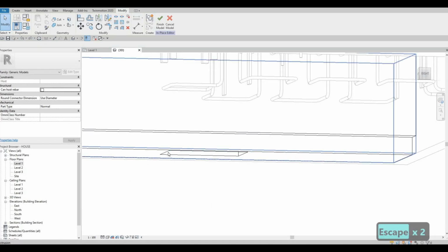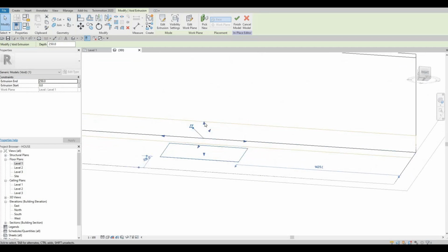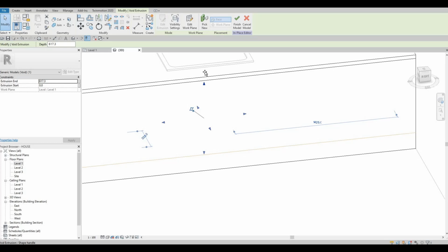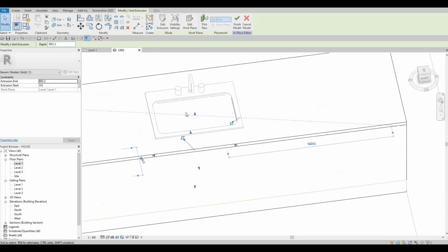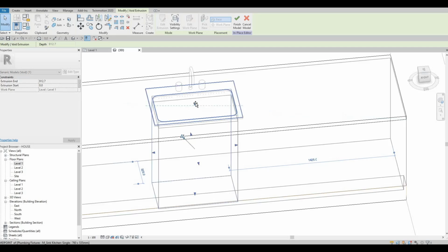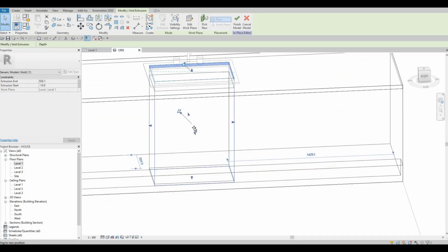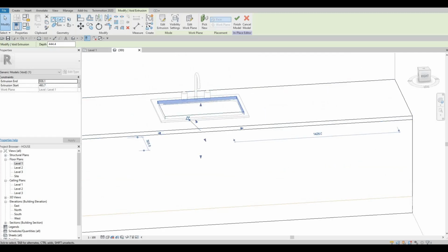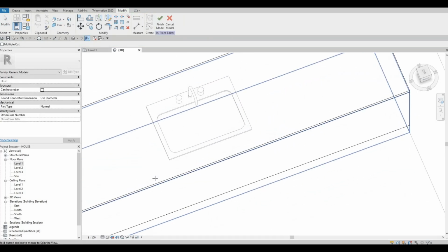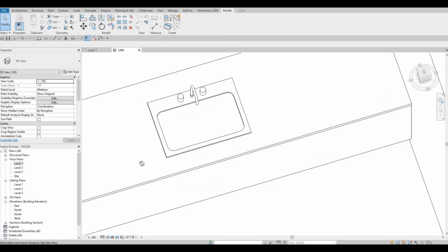The void form is right here. It's basically easier to select it from the bottom. Luckily, we haven't added the floors yet. What I usually do is extend it all the way at the top, and from the bottom just estimate it like that. Then after that, click cut, geometry, and then click finish.